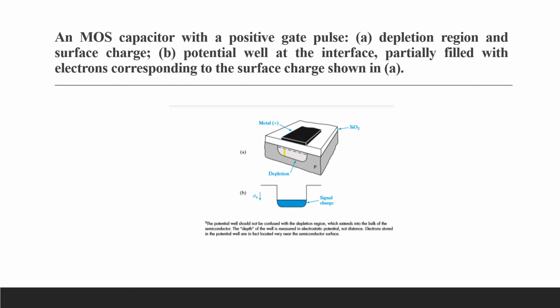If the positive gate bias has been applied for a sufficiently long time, electrons accumulate at the surface and the steady state inversion condition is established. The source of these carriers is the thermal generation of electrons at or near the surface. In effect, the inversion charge tells us the capacity of the well for stored charge.